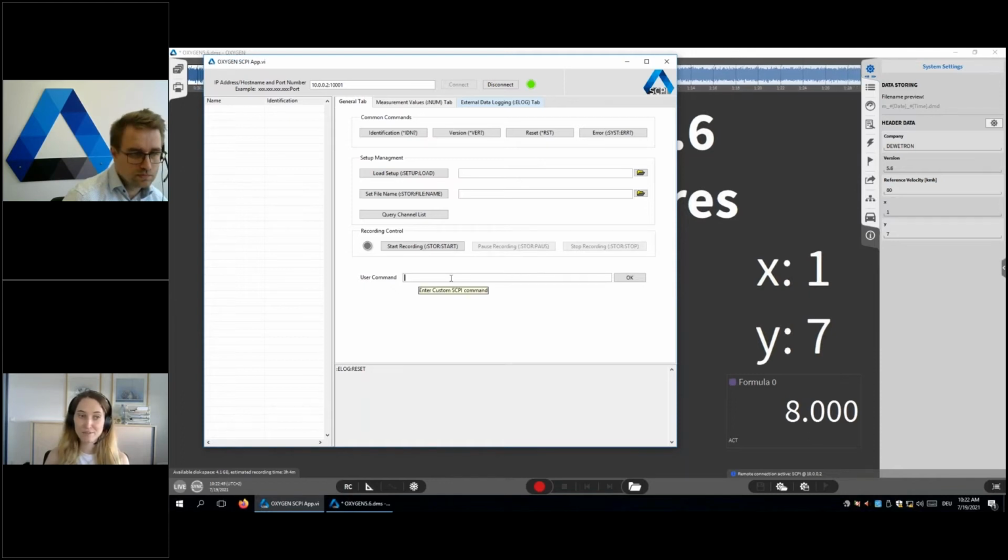To set a different value, we use the command set numeric constant. Then we want to change y, for example. Tell me a number. 5. Okay, click OK, and as you can see, y is now set to 5.